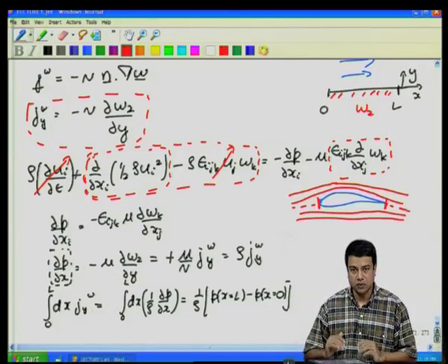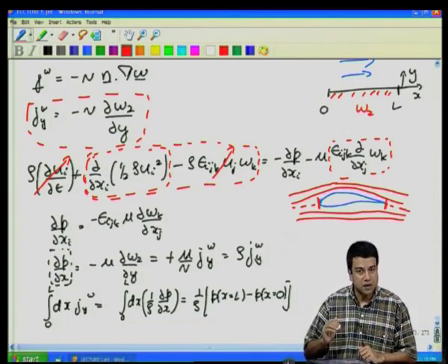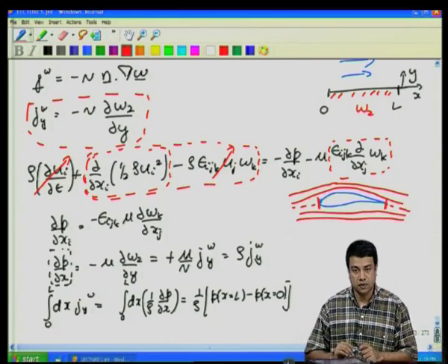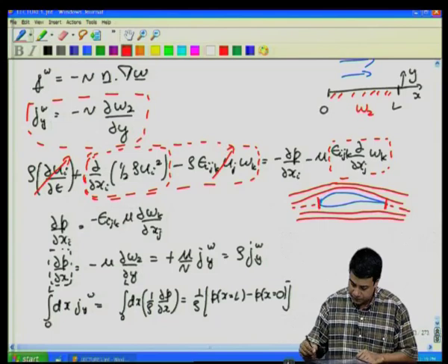What that implies is that for this particular case, the net amount of vorticity generated from the surface is going to be equal to 0, because the pressure on the two ends has to be the same. Therefore, even if you have a boundary layer, as long as that boundary layer is a confined boundary layer, the pressure at the two ends is exactly the same, and for that reason there will be no net vorticity generation from the surface.